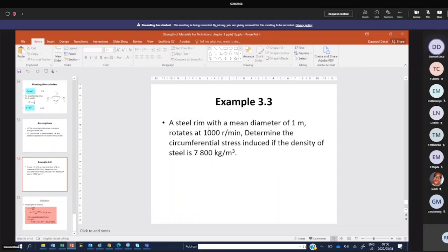There's an example on rotating thin cylinder. You get three cases here, people. I hope you listen carefully, eh? Very important to understand what I'm teaching. That's why you come to class, eh? You get three classes of problems for thin cylinders. You get a thin cylinder that is stationary under pressure. Okay, your deodorant can, fire extinguisher that's on the wall, use the normal theory I taught you. So that cylinder is under pressure, normal one, stationary, not rotating.